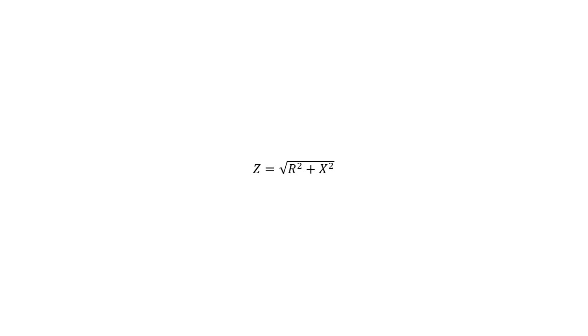High impedance devices, greater than 10 kilo ohms, include instrument outputs, generally between 7 and 20 kilo ohms, and interface instrument inputs in the 1 mega ohm range. Why is impedance important? Because in some situations, knowing the source and destination device impedances, where the destination impedance can also be called the load, can help resolve audio issues like loss of sound quality.